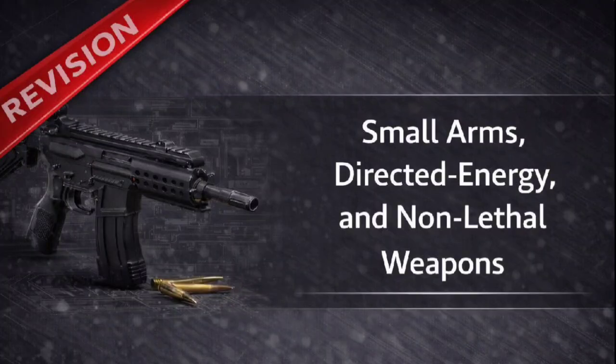Correct. The short-stroke piston moves only a very short distance, sometimes just a few millimeters. It imparts a sharp, powerful blow to a separate operating rod, which then throws the breech block backward. And this is better for rifles because... It's preferred for rifles because the weapon's center of mass is minimally disturbed. This greatly maintains weapon balance and the stability of aim during rapid fire.